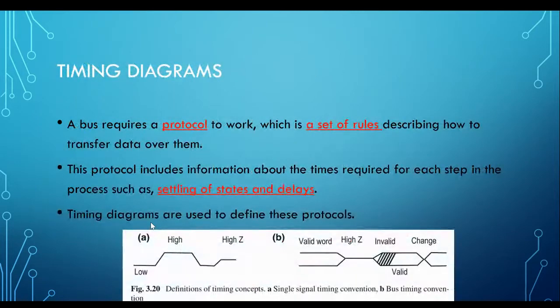Normally we only know whether the line is 1 or 0. For example, with I2C, you have a common bus, and that bus is normally 1 or 0. But in order to design this in a very practical manner, sometimes you have a third state. We call it the high impedance state. High impedance state is neither 1 nor 0.